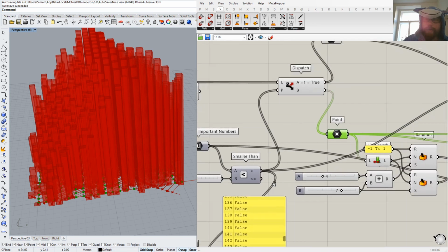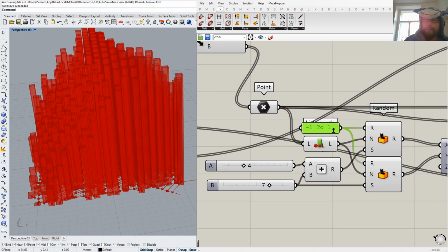Oh, this component with the random thing, I just double click and type 2 slashes. So I'm gonna make a new one and type it in there. If you start with these two things in the search box, that's gonna give you an opportunity to write anything in there. So I'm just gonna type anything in here and hit enter. You first need to have these 2 slashes, and then you can have a panel with everything in there.